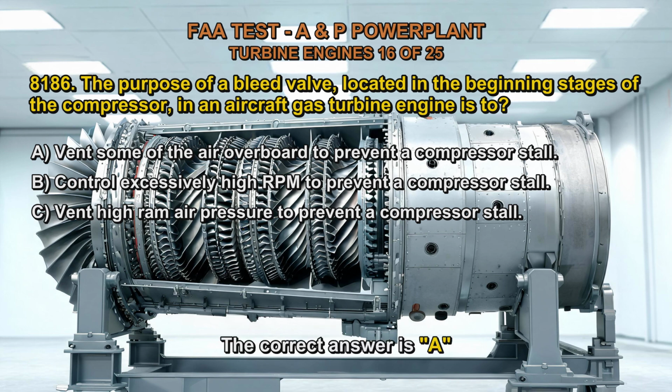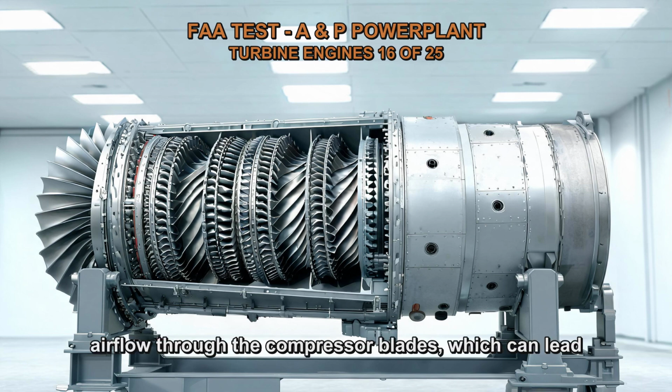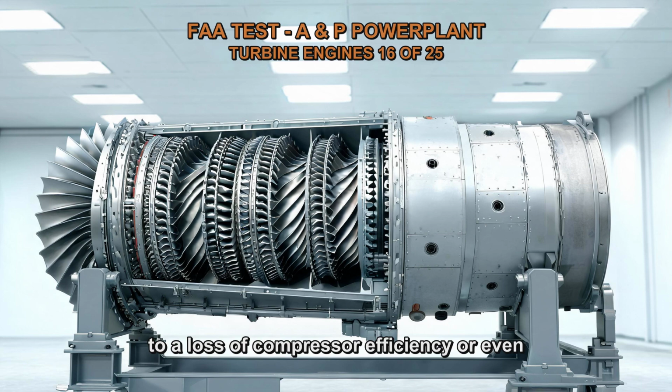The correct answer is A. The purpose of a bleed valve, located in the beginning stages of the compressor in an aircraft gas turbine engine, is to vent some of the air overboard in order to prevent a compressor stall. A compressor stall is a disruption of the airflow through the compressor blades, which can lead to a loss of compressor efficiency or even a complete compressor failure.